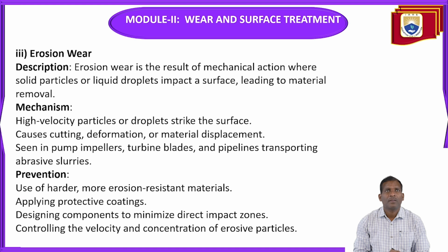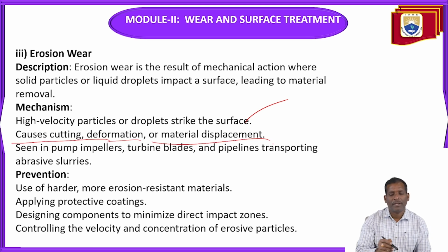Next, erosion wear. This erosion wear is the result of mechanical action where solid particles or liquid droplets impact a surface, leading to material removal. Examples are turbine blades and pump impellers, which are always subjected to liquid particles impacting. The high velocity particles or droplets strike the surface and cause cutting, deformation or material displacement.